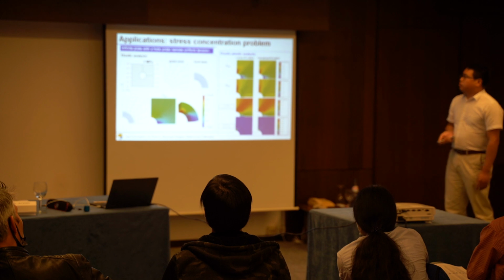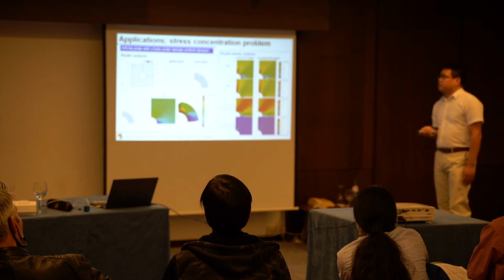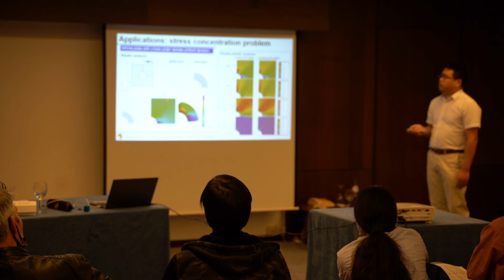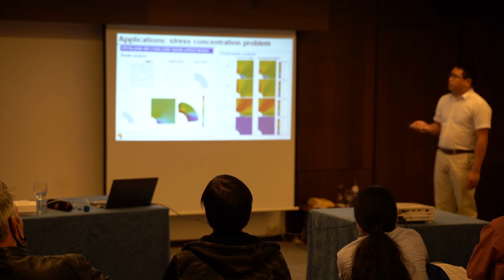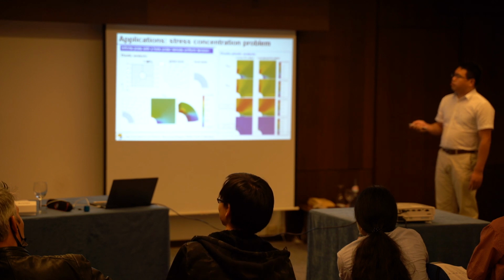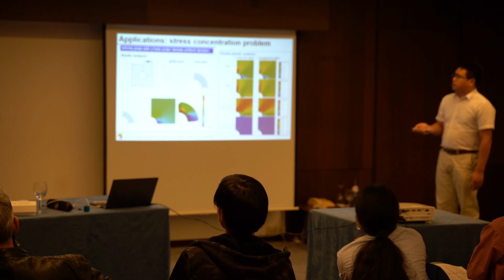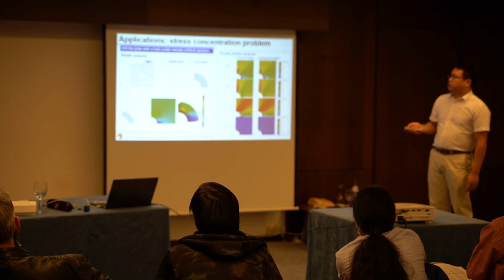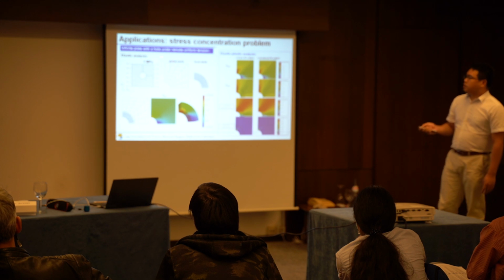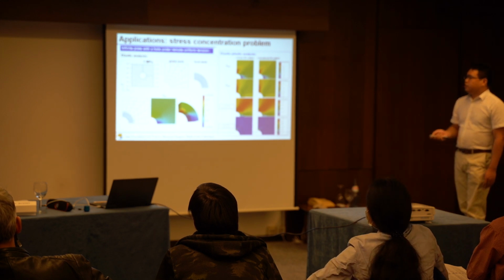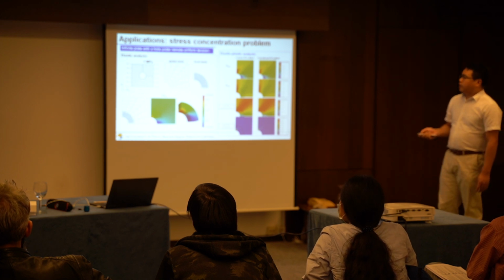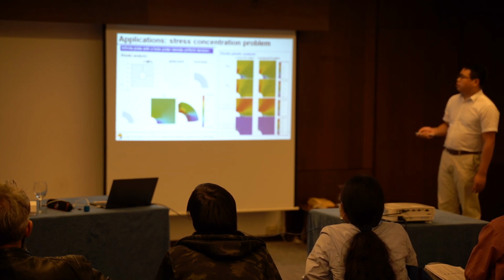And finally, we come to the applications. First is an elastic application to verify the accuracy of this method. We have a plate with a hole, and this is an elastic problem under tension stress of 1 megapascal. The analytical solution shows that the stress concentration factor here is 3, and we have this global mesh and local mesh. This is the superposed mesh, and we calculate the stress field, and the stress here is very close to 3.